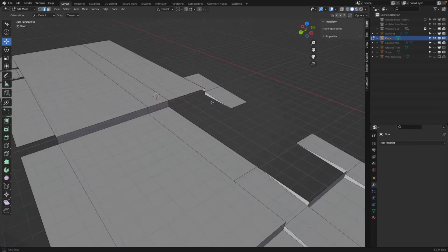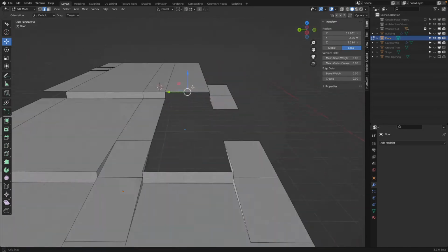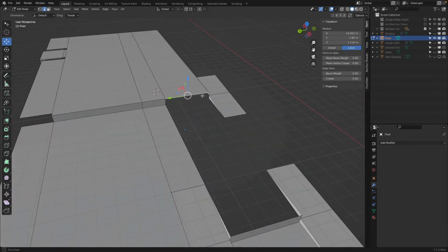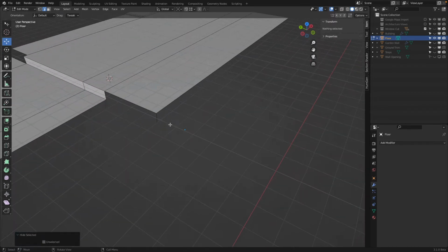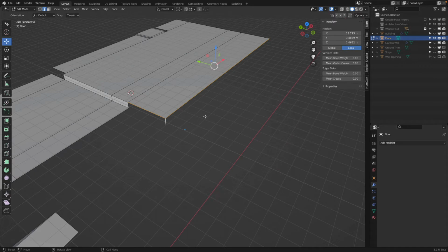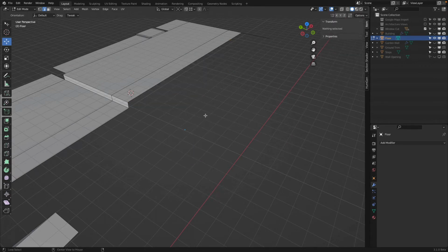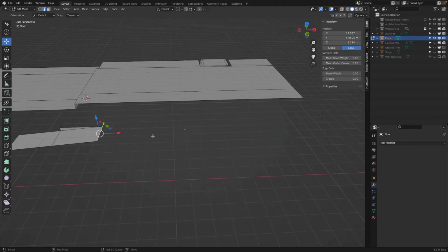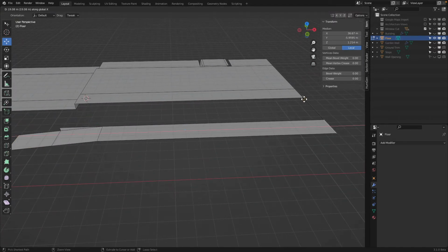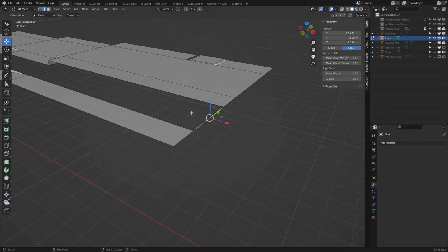yeah, delete this edge. Yeah, also select all this, L, and hide. Because honestly, this I need to remove for the moment, so it makes life easier. Delete edge. Alt H, show everything else. Very good. Now this is good. E and X, and I float this over to there.